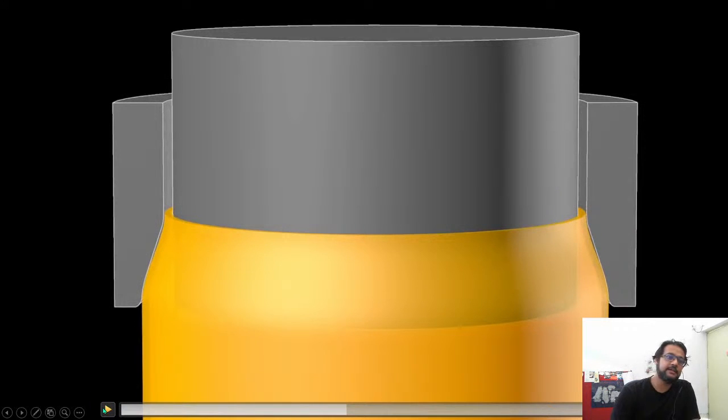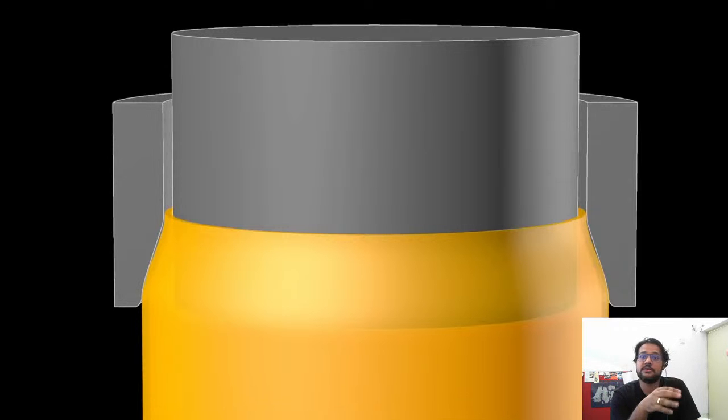So the reason that it happens in several stages is because the part has become so thin. I mean, because of these subsequent operations that happened prior to it, the material has become very thin. And what happens if you try to apply too much force and try to deform the material too much when it is so thin is that it will fold on itself and it will get warped.